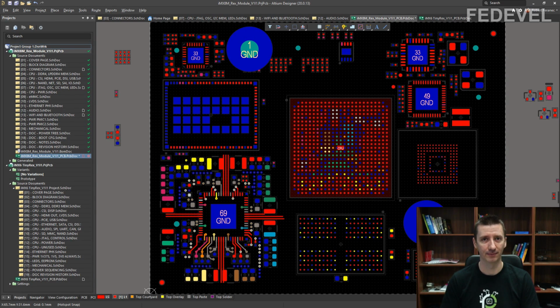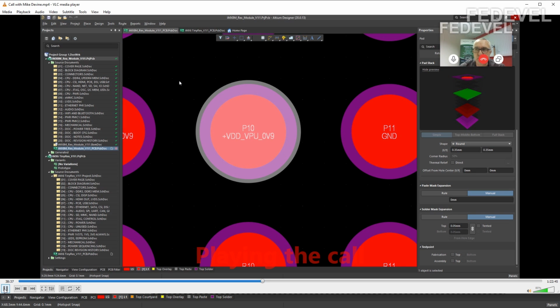Here is the clip. It is useful to have some kind of balloon drawing or demarcation, identification markings to say these vias need to be either copper filled or resin filled on the drawing. So yeah, a comment on the drawing to say vias in pad to be copper filled.